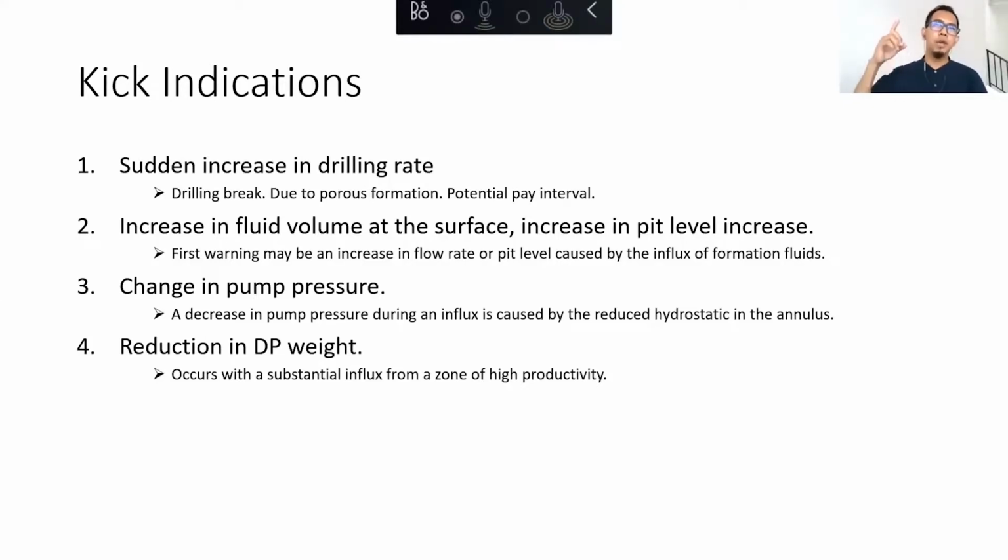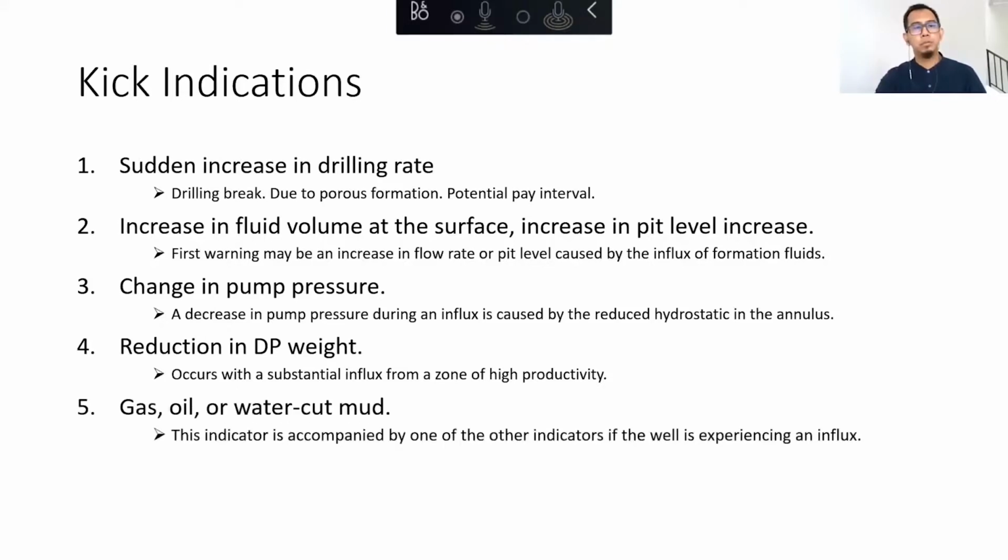So you hang it a little bit by the traveling blocks as you drill, and then if you want to drill faster, you give more weight by releasing the hoisting system a little bit. So that's it about the traveling block.